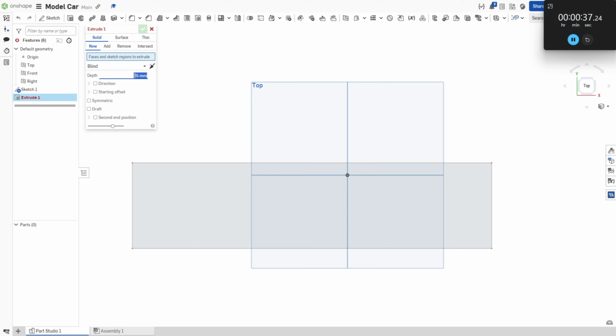The first section, from the windshield to the front of the car, has a diagonal length of around 108 millimeters. The middle section from glass to glass has a length of around 67 millimeters. And the final rear section has a diagonal glass to back length of around 83 millimeters. Finally, roughly measuring the wheel diameter, we get a diameter of around 35.6 millimeters.